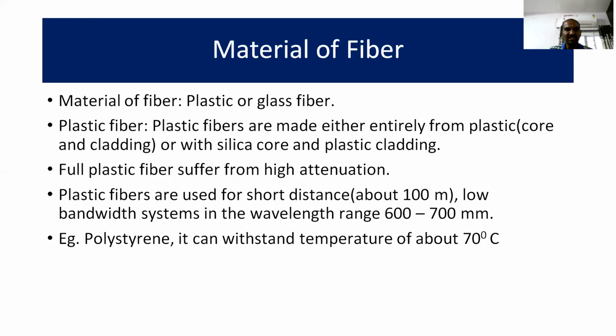Full plastic fibers suffer from high attenuation. Losses are more in the case of full plastic fiber. Plastic fibers are used for short distance applications, around 100 meters. These are also used for low bandwidth systems in the wavelength range of 600 to 700 nanometers. An example is polystyrene, and it can withstand temperatures up to 70 degrees centigrade.